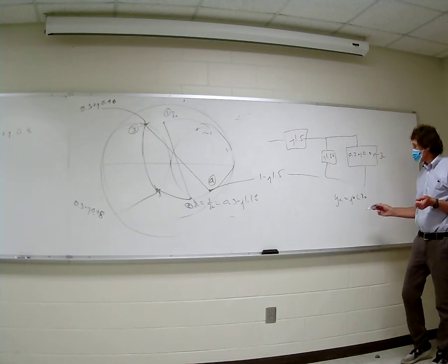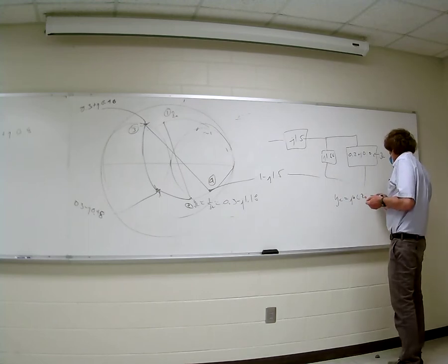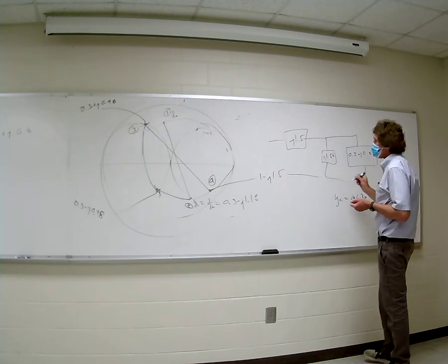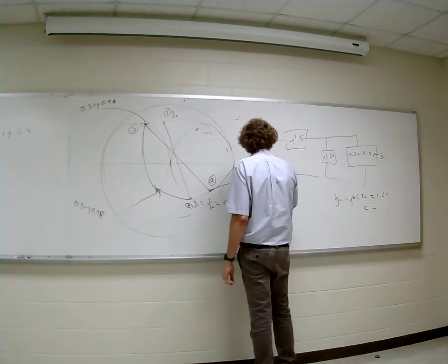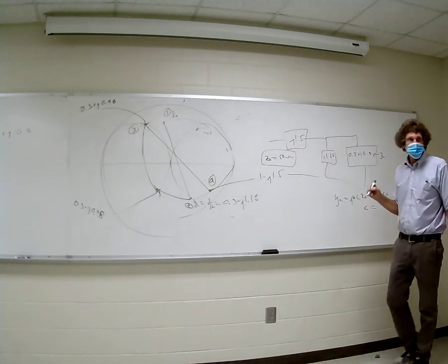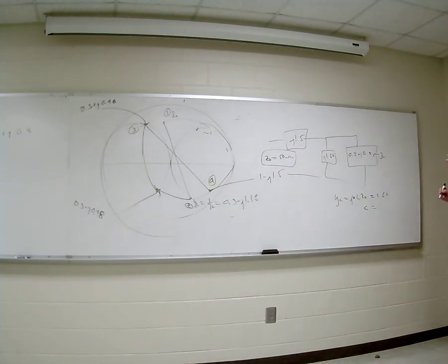We know the value. This is 1.66. Therefore, if we want C, I've got to give you a Z naught. I'll tell you the truth: Z naught is almost always 50 ohms for microwave work. Now, it's different with Charter or Spectrum or whatever, the cables. It's about 75 ohms for those cables. And there's a reason for that. It has to do with the breakdown strength and things like this. Typically, for microwave work, if you're building things, 50 ohms is a standard used for everything. You buy stuff that's standardized, 50 ohm cabling, 50 ohm everything.